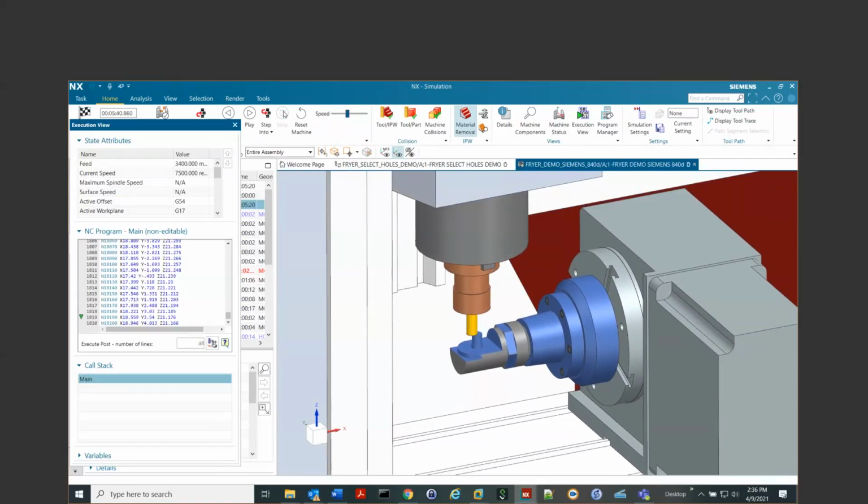But since this pillar is kind of high, I chose to use the other option, which is the spiral helical down onto it. I do that because if you leave this in adaptive milling mode, when it gets towards almost the end of cutting off that pillar, if it's so high, it might pop off and not cut off, leaving a crater in my part, and worse yet, breaking my tool. So I'm just going to spiral down on that.